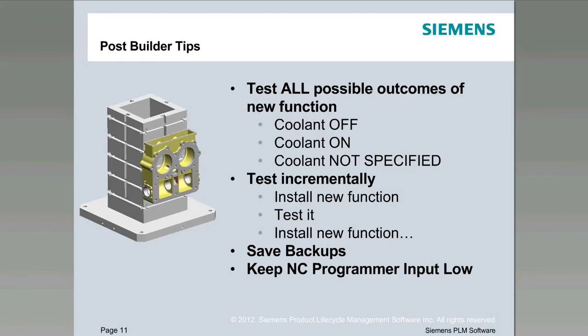Always save backups, and my goal is to keep the NC programmer input as low as possible. So while the user-defined events are really cool and I love to add them, if I can figure out a way to make the post understand how to turn something on or off, I'll do that instead of making another dialog or a button for the NC programmer to push.